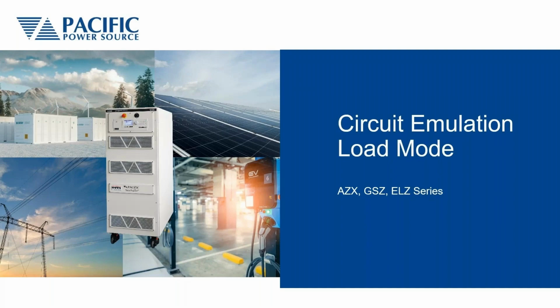There is the circuit emulation mode, which is an electronic load mode that allows you to create multiple permutations of RLC networks and simulate those on the load. So it gives you the ability to create a multitude of linear and some nonlinear application loads for test purposes.